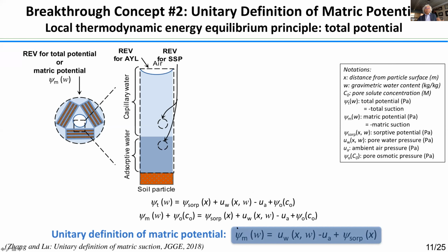And you will find that actually the matrix suction, or matrix potential, which is the negative sign for that, truly reflects how low it is in comparison with fresh water. It is this equation. So basically, we are going to have a capillary part, but we also have another part which is due to absorption. And the absorption is basically converting this energy to this one. But how much it converts depends on what kind of environment we give it. In other words, what we call the matrix suction.